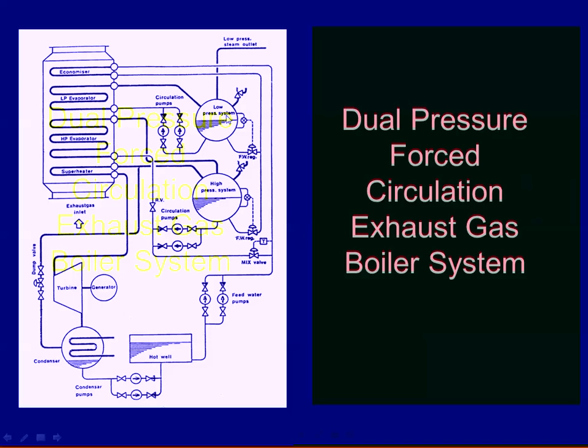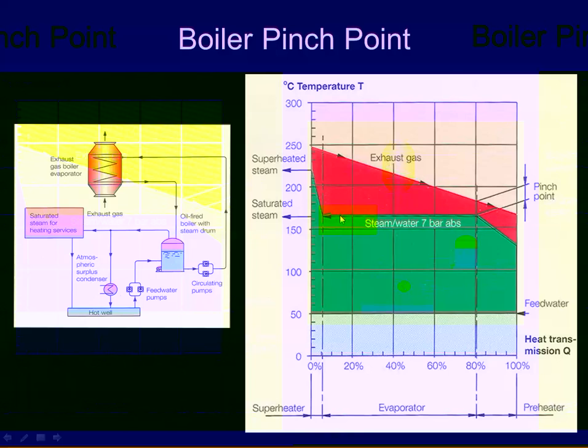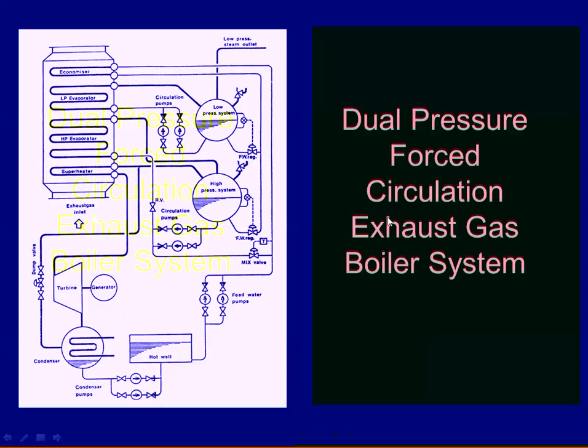What that means is that I will have two different saturation temperatures, which equate back to this shelf here, right? That's why this is flat, because the water is boiling into steam, and so that temperature is not going to change as long as material is changing state. But with this, I have two of those relationships, and I can increase my delta T.